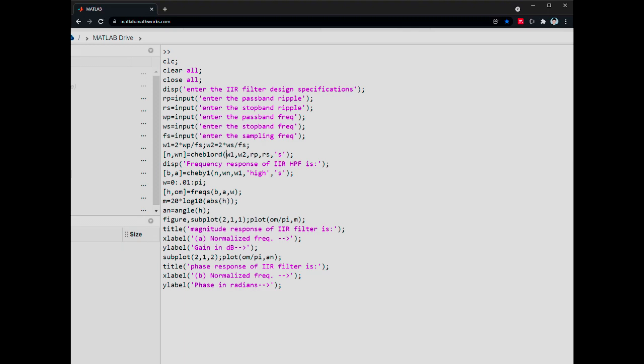The difference is here. The function used for Butterworth is butter. In Chebyshev we will use the cheby1 function, using the inputs of the Butterworth, but with a W1, or the WP, the passband of the Chebyshev. So this is the difference between the Butterworth and the Chebyshev methods. Here we need to apply the WP.